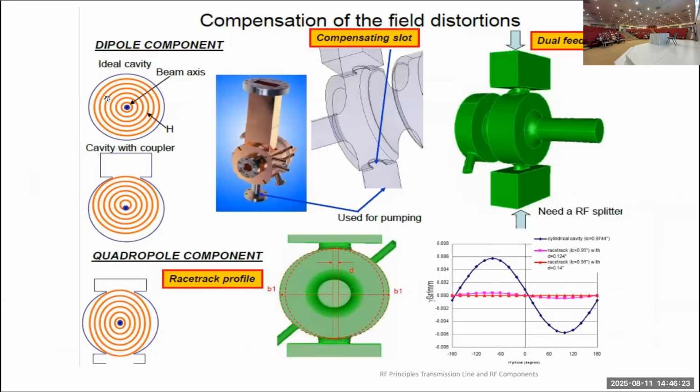I understand. So you feed the accelerating structure from both arms. Can you feed it with one arm? Yes, we can feed. And the second arm will be a plunger? No, there is no need of a plunger. A plunger is needed where you have to distribute your RF power. You want to send 10% of RF power to the structure, or 20% or 30%. It is in the waveguide assembly, not with the coupler to the accelerating structure or accelerating port.